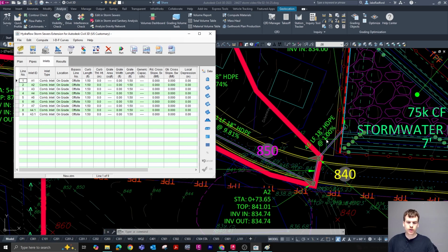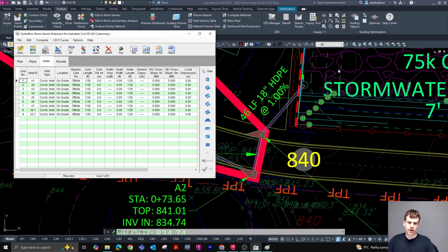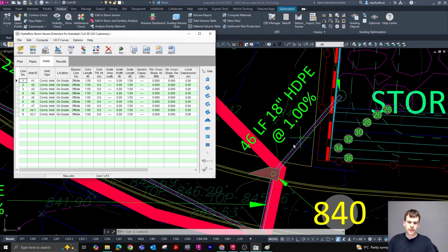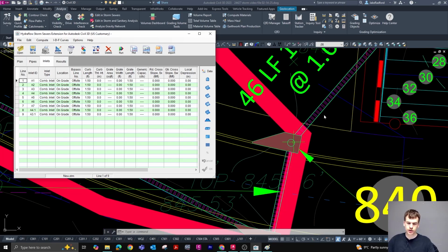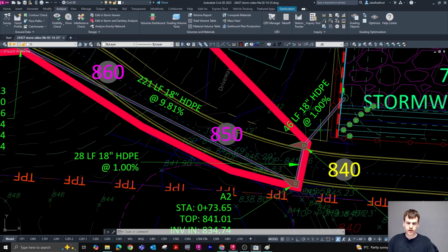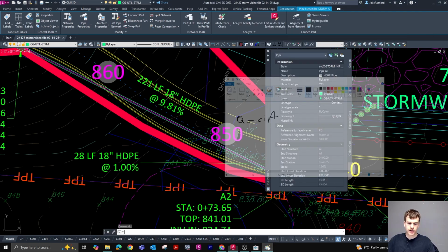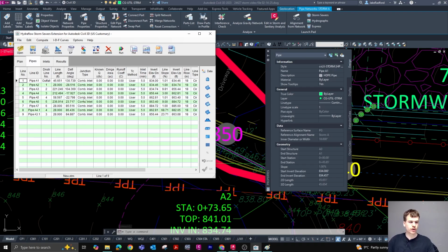If you remember, in one of the earlier Civil 3D pipe videos, I discussed the naming convention that we use for pipes. We always name our pipes in accordance with the most upstream structure that pipe is connected to. So for example, here at our outfall, this outfall structure is our structure A0, or our outfall. This pipe here is not named pipe A0, it's named pipe A1 in correspondence with the upstream structure that it's connected to. So this is structure A1, and if I select this pipe and drag over my properties pane here, you'll see that this is named pipe A1. Now, when we export into our storm sewers, our names are going to get exported with all the other information under line ID.